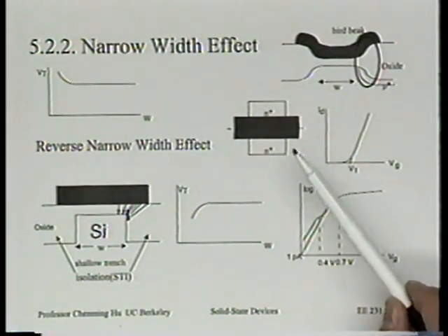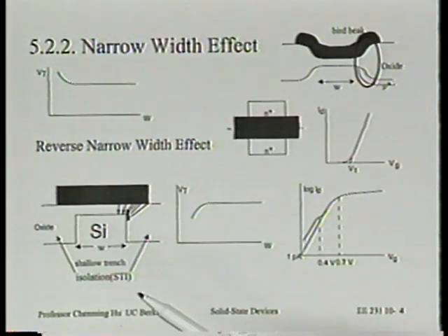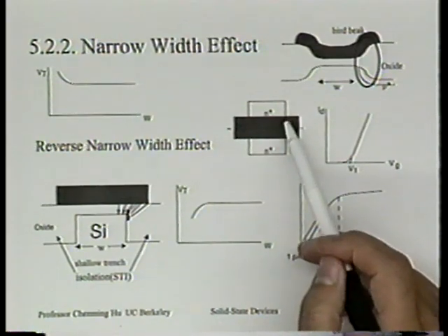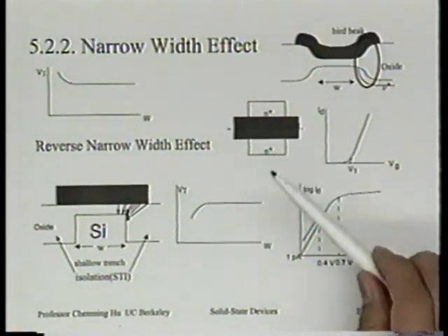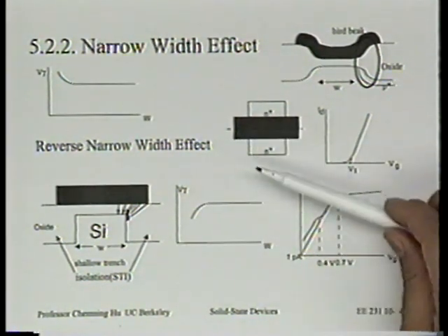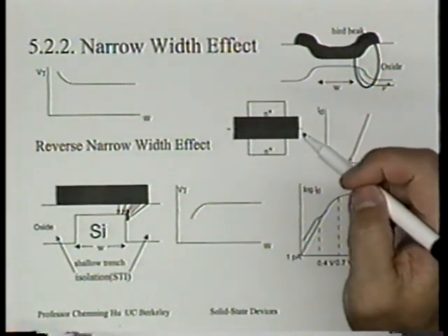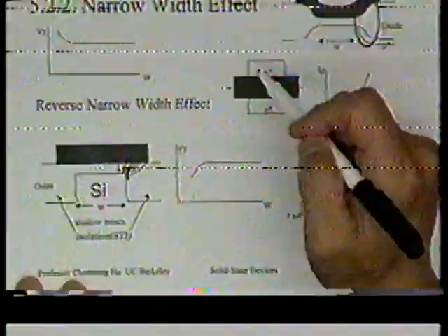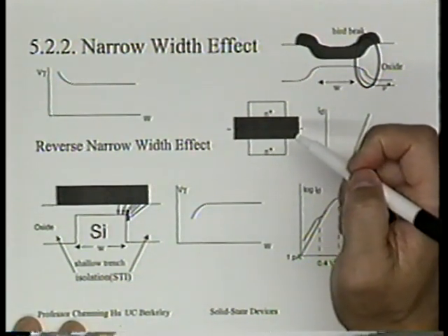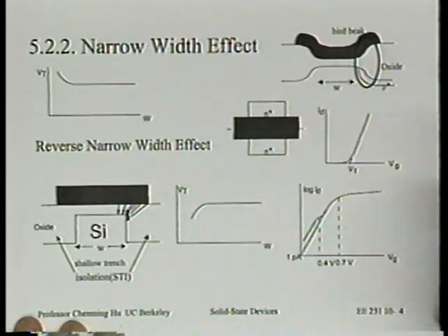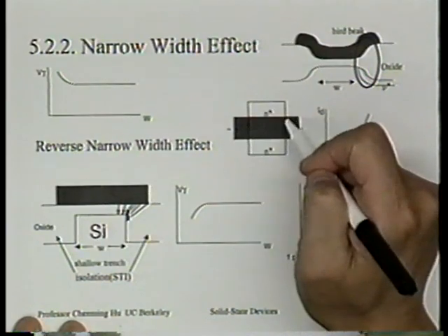All right? To one side, you see the source. To the other side, you see the drain. I call them N plus source and drain. Is that right? Anyway, let's just say this is what it is, all right? What defines the source drain region is the following. At the risk of complicating this, let me complete this box that encloses the source drain region, completed for the portion that's hidden by the polysilicon gate. If I complete that, there's this region that you can visualize that's rectangular, all right?